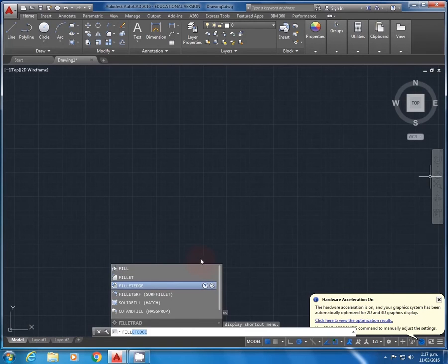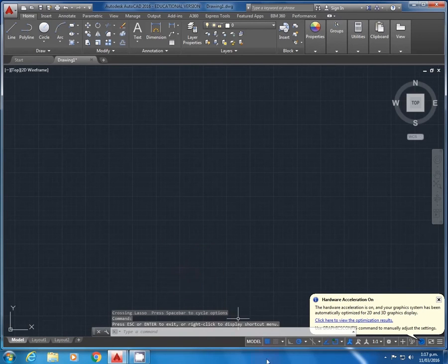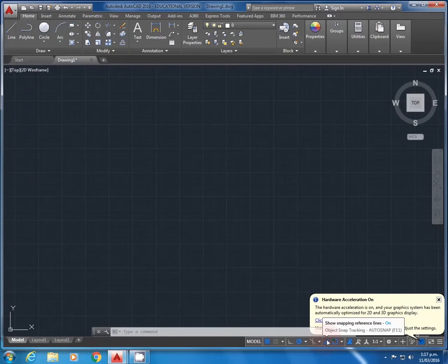And this is your quick access toolbar, which has things like object snapping, your annotation, whether or not you want to draw in ortho mode, which is everything's going to be in 90-degree angles, I guess. Yeah, so this is basically what you'll be dealing with throughout AutoCAD.